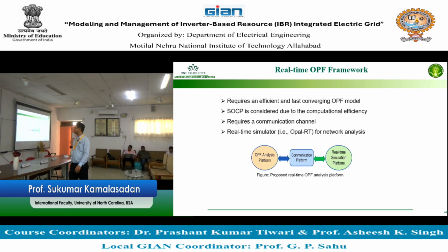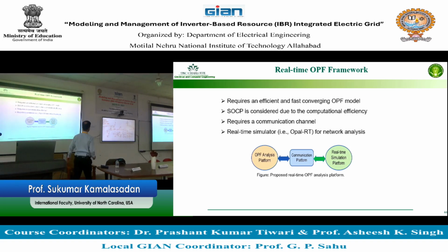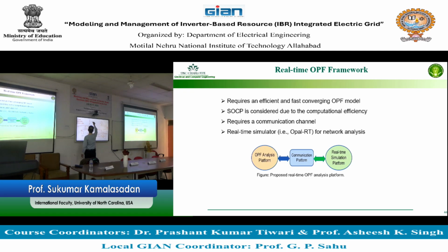So let's write it. So OPF or PF sends a signal, P set, V actual, to the field and collects back P net, which includes PL, PDER, and network topology.